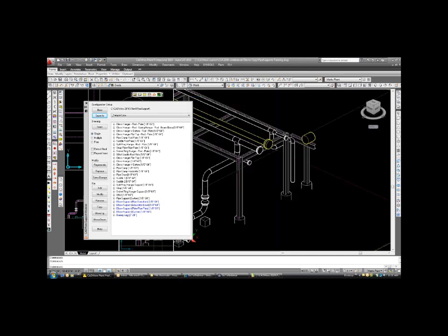Now, basic functions. When we go to insert a particular pipe support, we will use this Insert button and we'll insert them either as a multiple or single, or just kind of freelance and put it wherever we want to put it out in space, or on any pipe. We also have the option to detect steel and repeat the insert. And when we want to modify a support, we can come down here to regenerate it if we've made a modification to the data file, we can replace it with another support, or we can do a spec change on it if we've changed spec on that particular line.